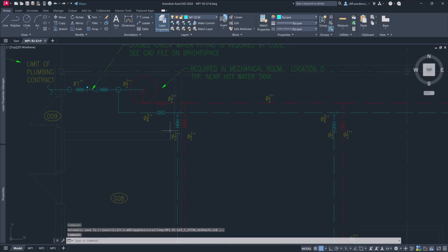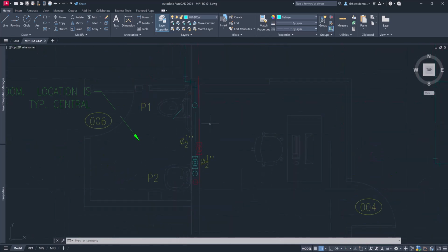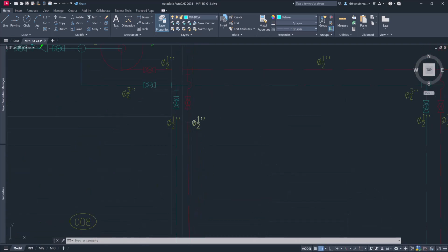Right. I don't expect you to get this all at once. If you have questions, please ask. But that's how you size hot and cold water. Right? And again, the thing that I'm asking for you guys to do is, you place them wherever you're going to have basically a change in the length of the pipe. Place them. This one for the hot water, I did run a 1/2 inch and a 1/2 inch to make it clear on what you guys have, but you would only need one section along this pipe.